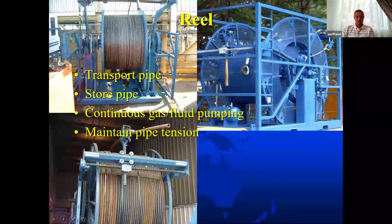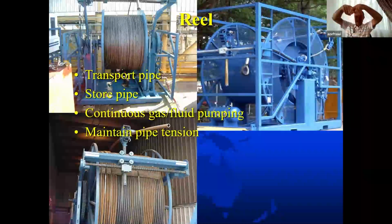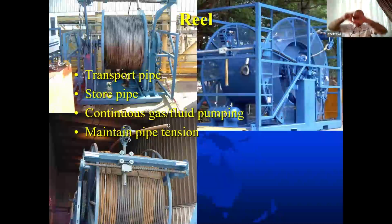If you notice here on the drum, we have a device we call the override. The function of it is to spool the pipe correctly on the drum. So when we spool while pulling out of the hole, the pipe will be together like that, but it won't be over each other.